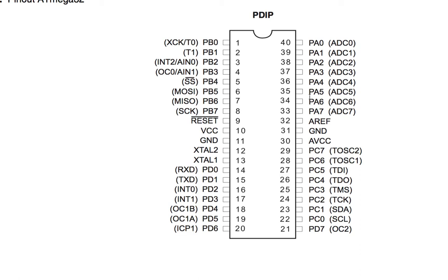There are about 7 steps that you can follow if you want to program analog digital converters of an AVR microcontroller. In this case, we're talking about an ATmega32 or ATmega16 because these two are very similar. The first thing that you need to do is to make the analog digital converter channel pin an input. You declare it to be an input channel.